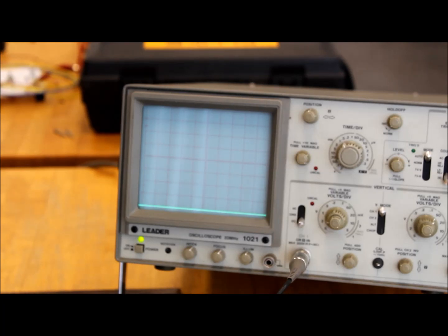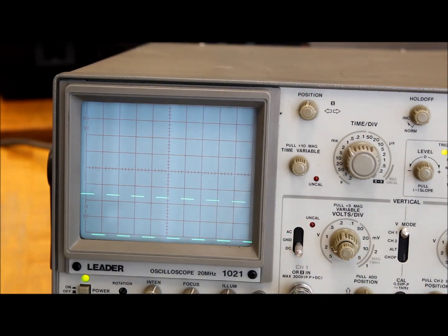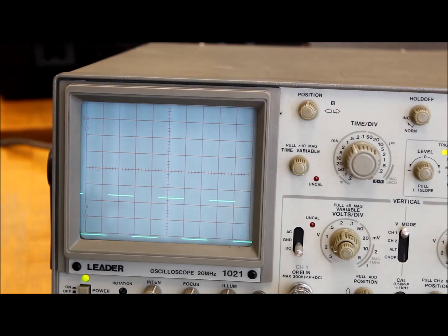We're not going to use a 9-volt battery. What I have here is a signal generator board. I have this signal generator board set up right now. It's putting out a digital square wave signal, and I'm just going to focus in on the scope screen and see what that looks like on the scope. So here you can see I have a digital square wave. It's off here, on, off, on. I can change the timing a little bit, make these a little bigger or smaller, maybe make it a little bit easier to see. So that's the signal that's coming out of the board as measured by the scope, and it's putting out about 5 volts, 2, 4, little under 5.